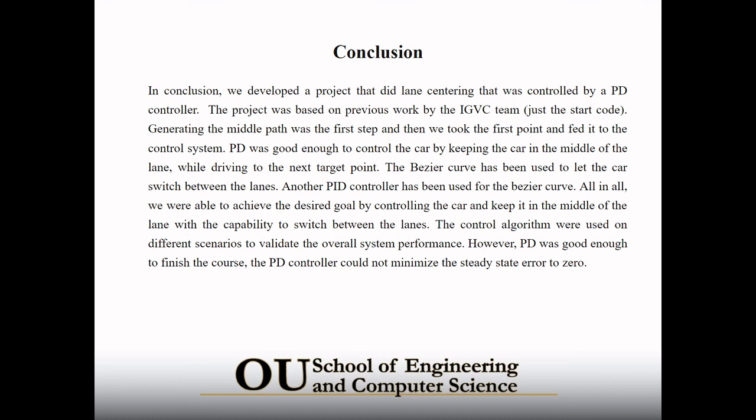Then we used a Bezier curve followed by a PID controller to make sure that the car follows the curve generated. All in all, we were able to let the car drive successfully in the center of the lane and remain in the middle of the lane, and also switch the lane safely without an error.